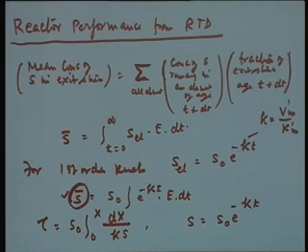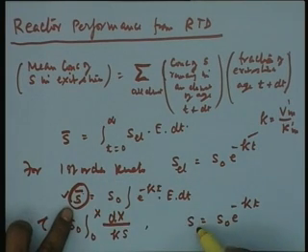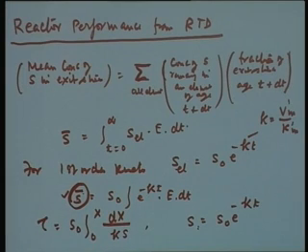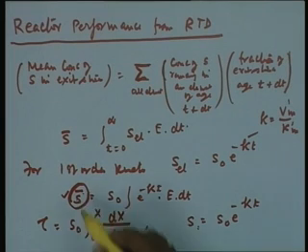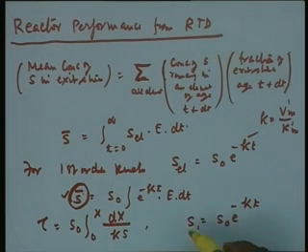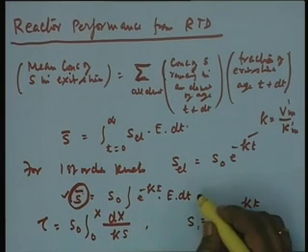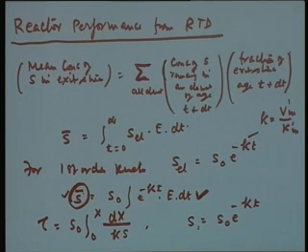If it is an ideal plug flow, the closeness of these values S as well as S bar will indicate the ideality of the reactor flow pattern. But in case there is a deviation, one will find quite different values, and obviously the actual reactor performance will be judged by the residence time distribution and kinetics combined, taken together.